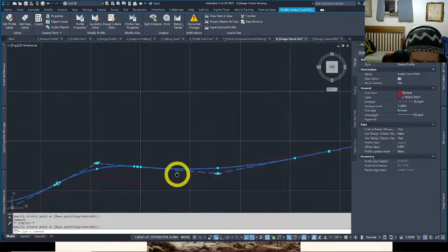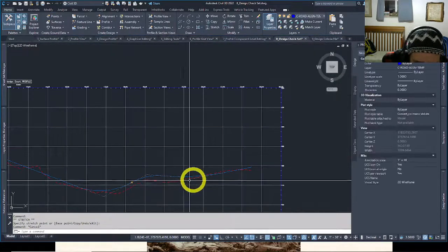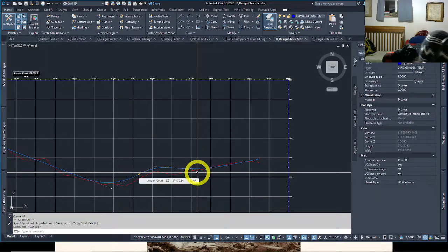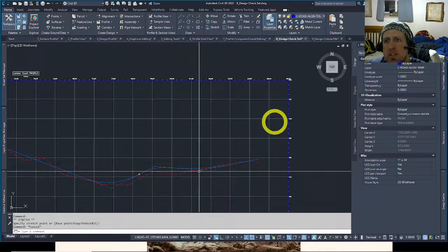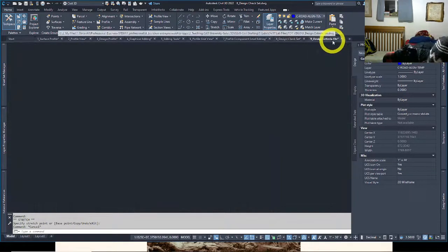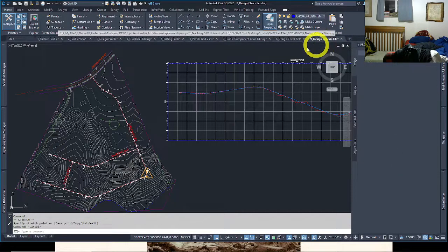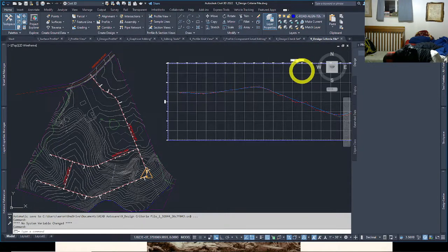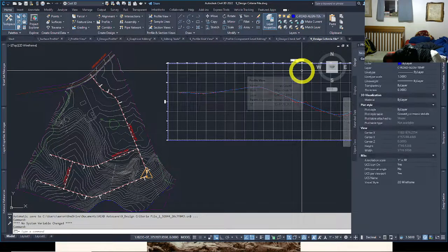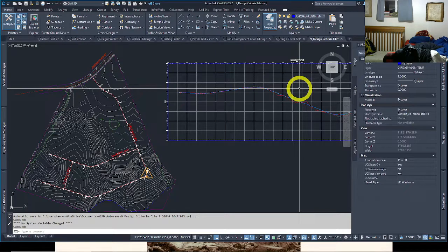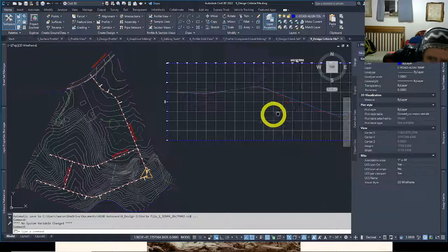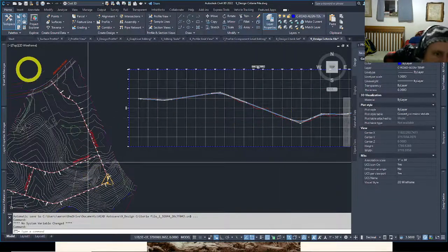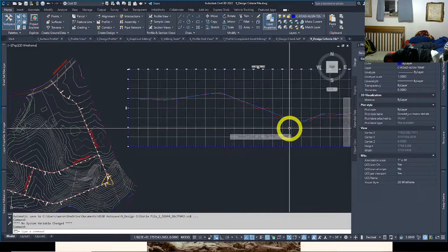Anyway, that is good enough for now. I got 2 of them gone. I'm not going to fight the other one much longer. We'll move on to the last area of this chapter, design criteria file. So we edit that. Same as we did with alignments, you can assign a design criteria file to a profile too. It gives a general behavior within the criteria file. So as the checks, they display warning symbols, tell you where the parameters are not met of your profile, similar to alignments. They work similar.